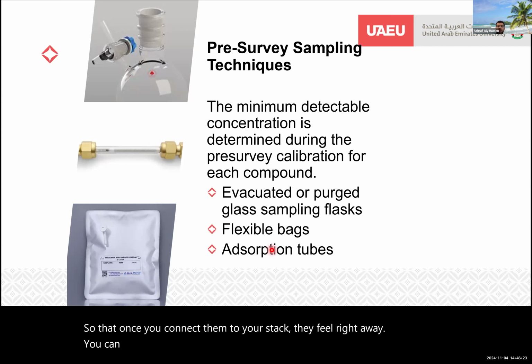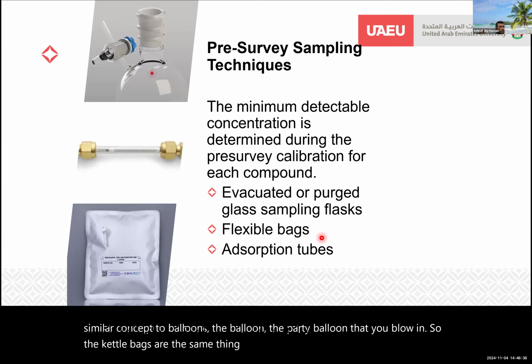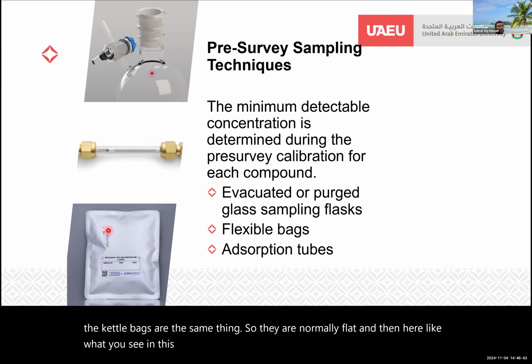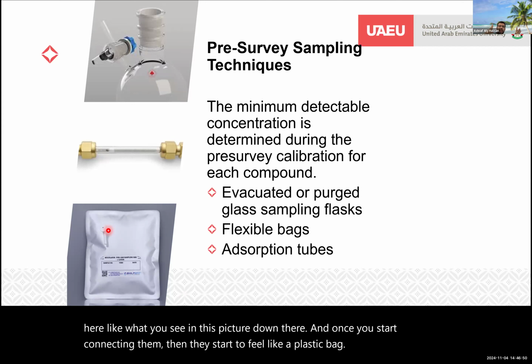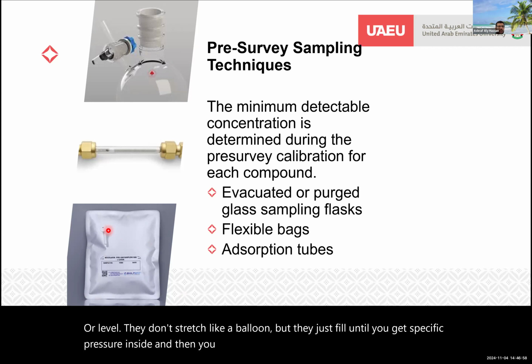You can have flexible bags, what we call Tedlar bags. These flexible bags are a very similar concept to balloons. You know the balloon, the party balloon that you blow in? So the Tedlar bags are the same thing. They are normally flat, like what you see in this picture down there. And once you start connecting them, they start to fill like a plastic bag or a balloon. They don't stretch like a balloon, but they just fill until you get a specific pressure inside, and then you close it and you take it to the lab.